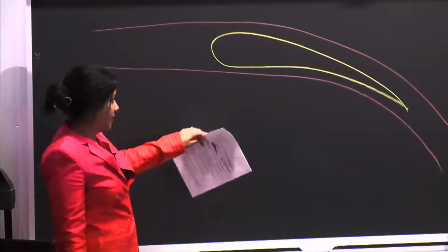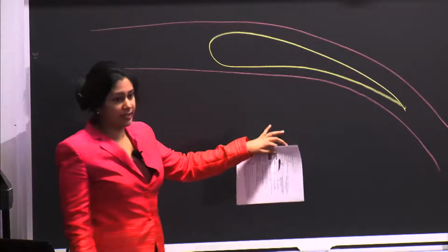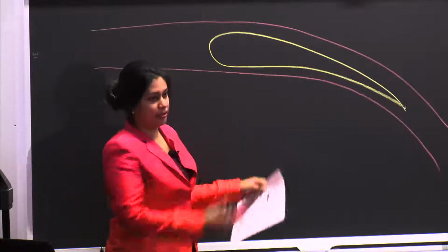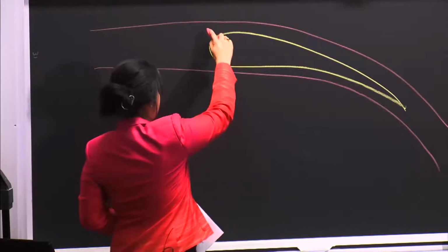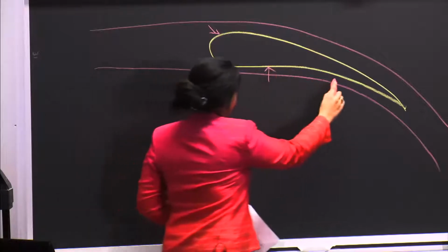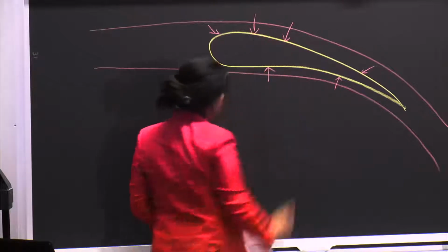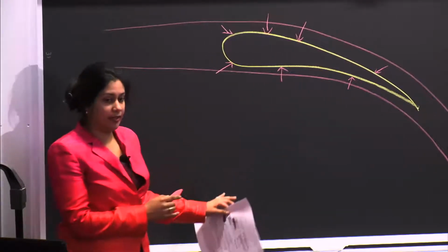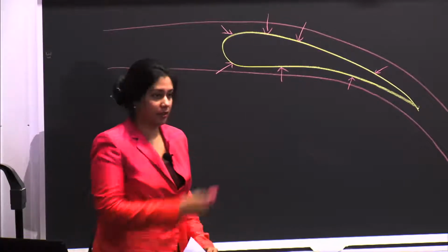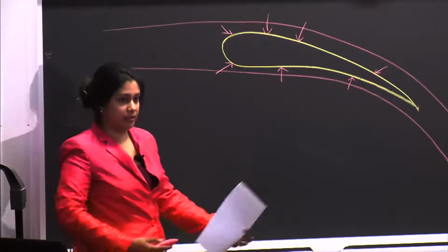Okay, so when you have this airfoil in a fluid, when the fluid is stationary, all of the fluid is exerting pressure on the airfoil. So you get all these little normal forces exerting pressure. When the fluid's not moving and the airfoil is stationary in the fluid, then all of those pressure forces, those normal forces, or forces perpendicular, sum to zero, because there's no net force.